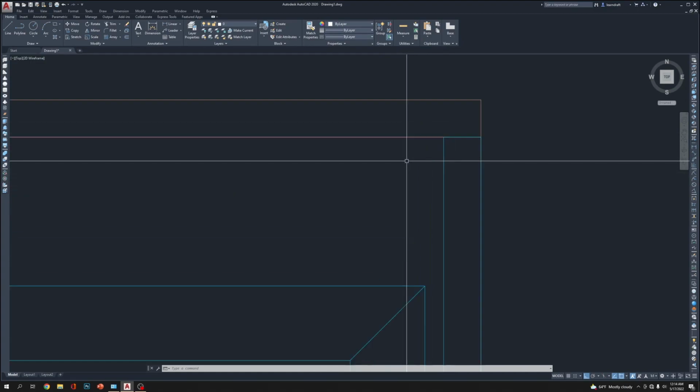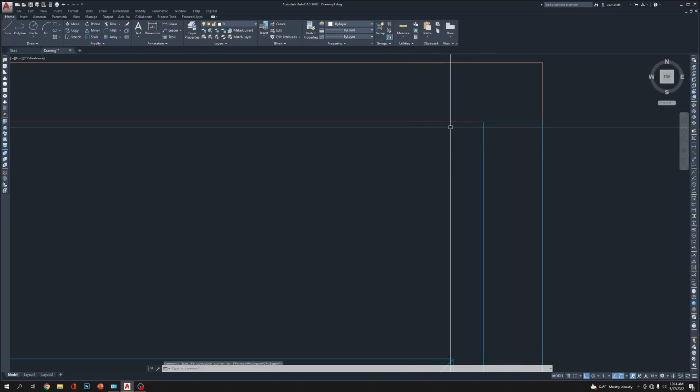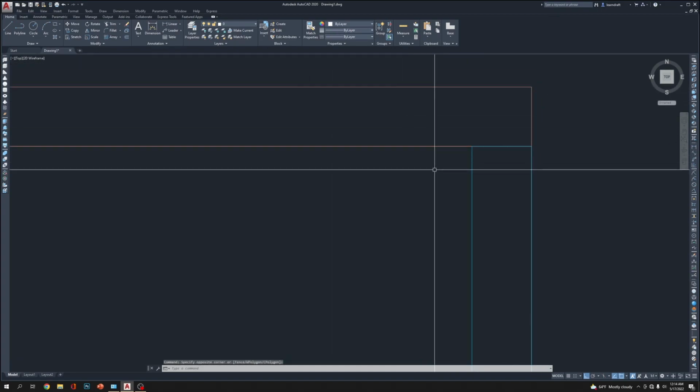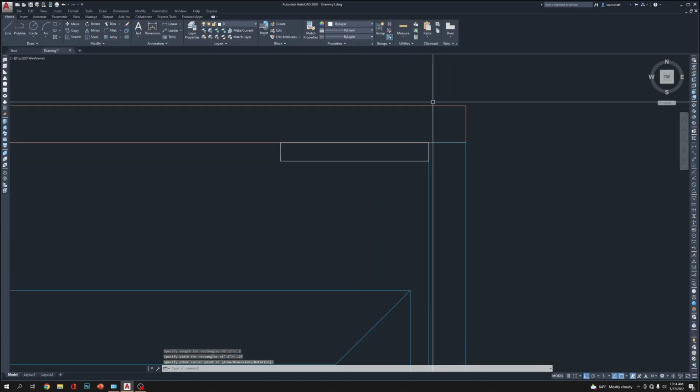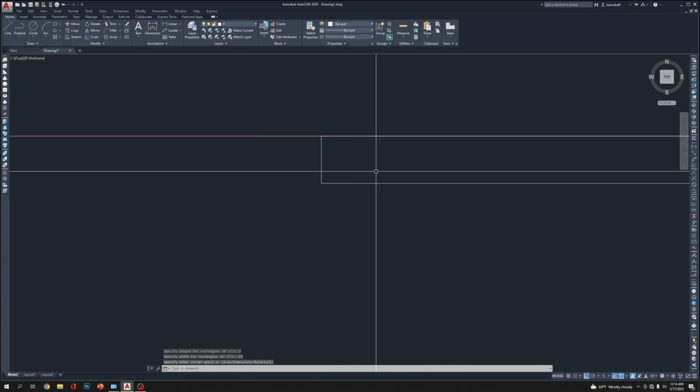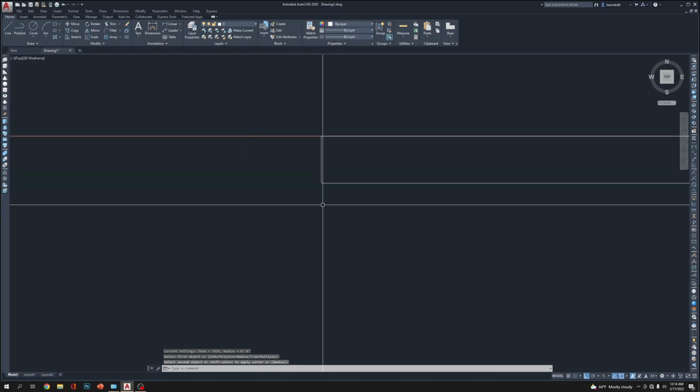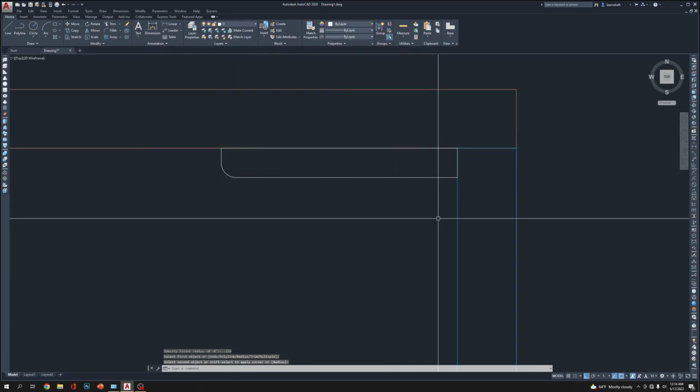So we are going to place a mechanism here to hold this one. So let's say I'm going to draw a rectangle. Dimension is like 2 by 0.25. Fillet, let's see if I can fillet it. Fillet radius 0.125, enter, click here, click there, other corner no, only this one.